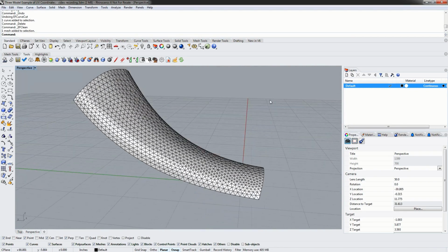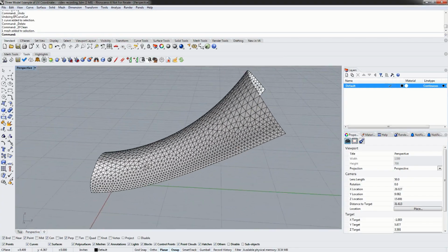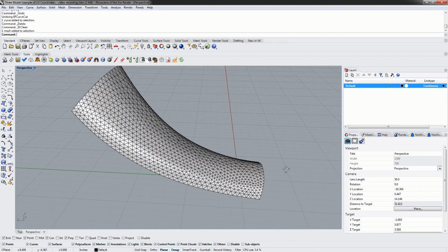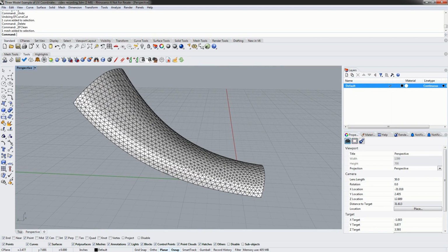To begin, we're going to angle our camera into a position so we're looking at the mesh where we want to create the cut. For this one, I'm going to create a V-shaped cut right along the surface here. If I create a curve in our viewport, Rhino is going to project it along the axis of the construction plane, which doesn't follow the direction that we're looking at. So the easiest way to solve this is to create a new construction plane, a new grid that is perfectly parallel to the view right now.